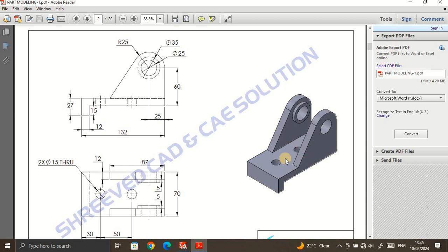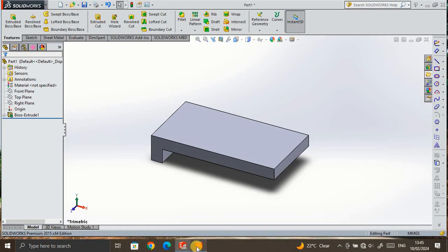The two vertical plates are exactly from the mid, both having a similar shape. For the 3D mirror, we initially need to select the mid plane, but in this plate, when we see the front plane, top plane and right plane, we extruded the part from the front plane in one direction. So again we can change this.